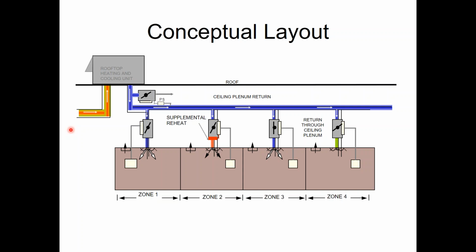The other problem, specifically at that job, is every time a new building engineer started working there, a couple months later we had to go back out to the job and fix everything. Because they would automatically go change everything to 55. Like, why the hell is this set for 47? What the hell is this guy thinking? It's a waste of energy. And they put it at 55. The next week they'd be working on the chiller and ask why it's set for 39, and they'd set it back to 44. They'd keep fixing it because he was the new guy and he made it like every other building he serviced.